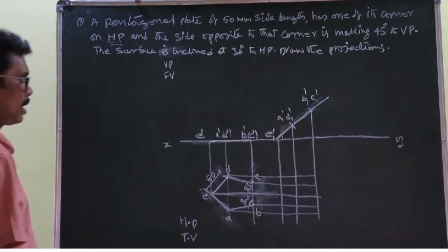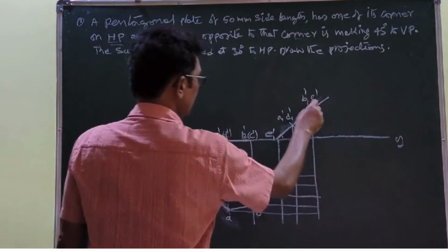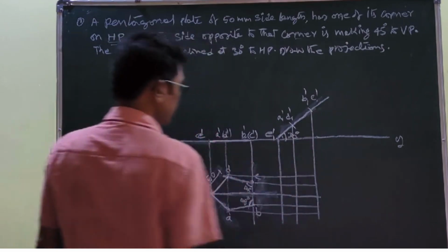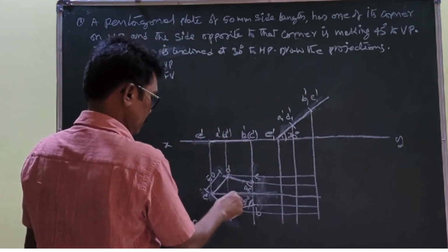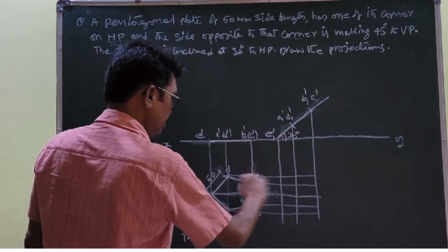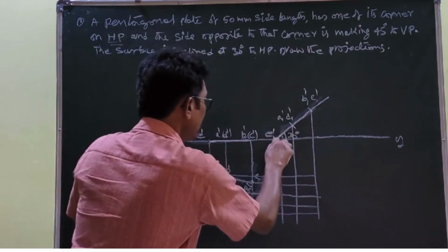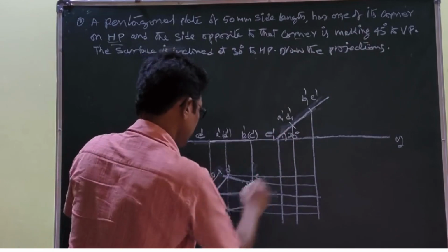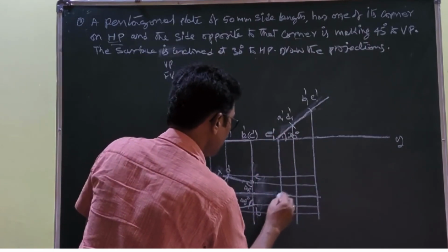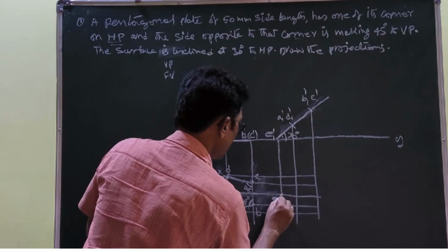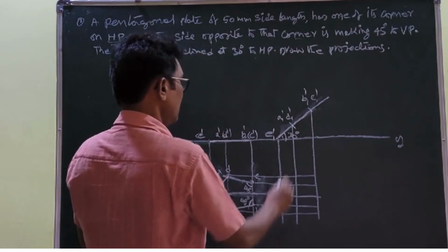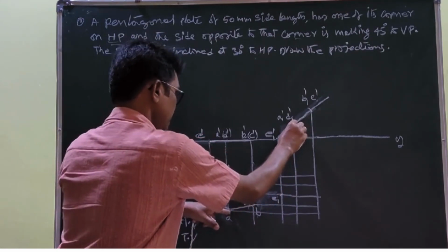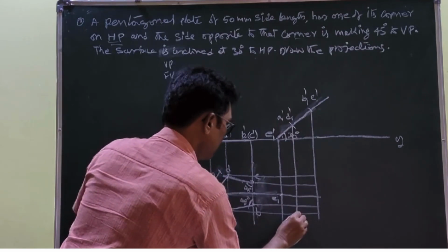E. Like this you draw vertical projections from this front view, and it is making an angle of 30 degrees from this top view. You draw the projectors. Then once you draw the projectors, E1 dash and E dash, they meet at this point. Let us say this is the E1. A dash and A1 dash, they meet at this point.